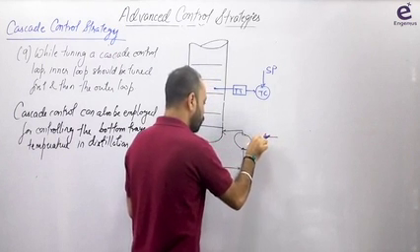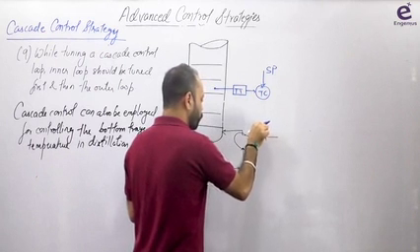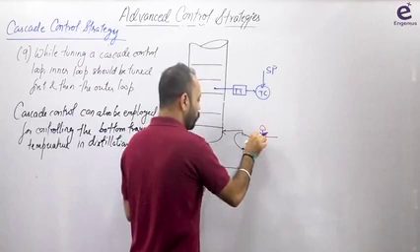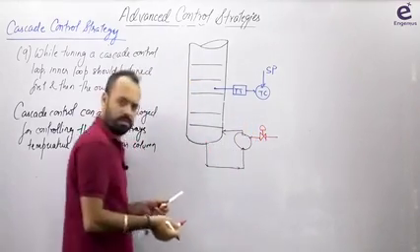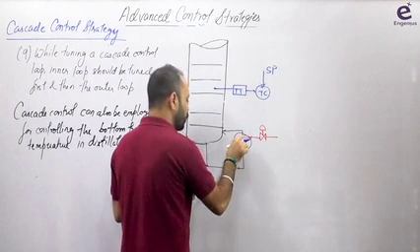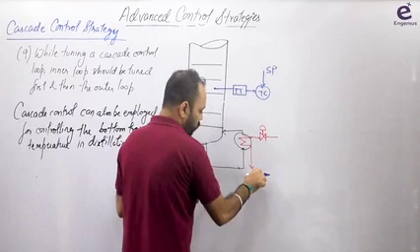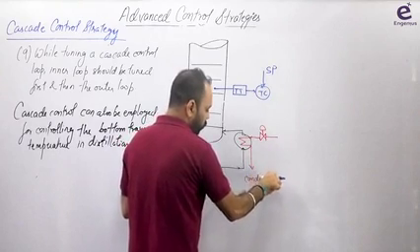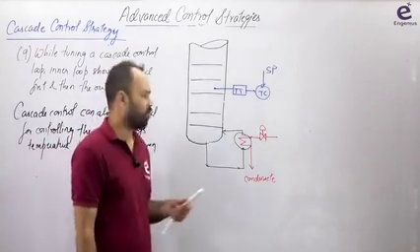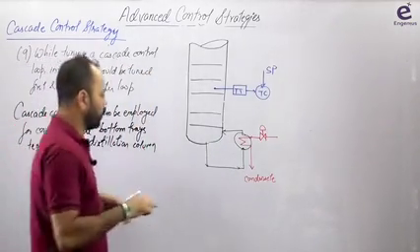Steam is always taken from some steam header. I mean, steam is coming from some other process, some other header. Okay. And the steam header is used to provide steam to various processes. This is the steam which is coming, and then it is used to heat, and then the steam is leaving. Condensate, you can say. Not necessarily condensate. Generally whenever you use steam, you use its latent heat. That is why I'm writing condensate. So steam is coming from the steam header. Okay, this is steam in.